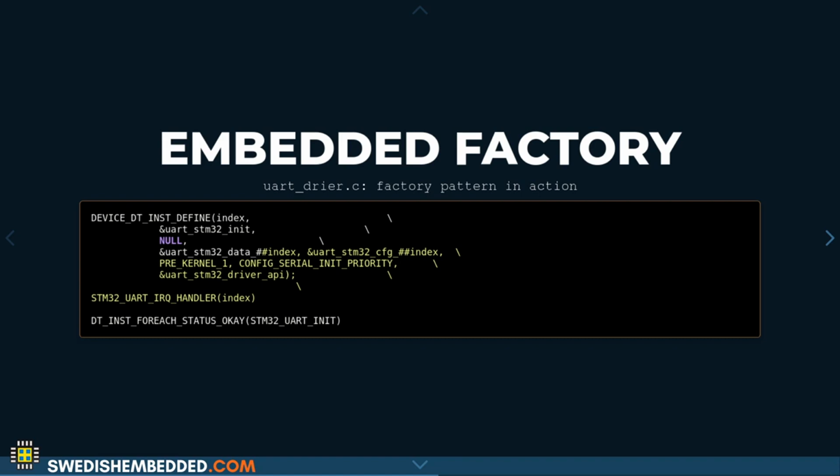This is a name that I've just created because I think this is a pattern that is very commonly used in embedded systems when you need to create objects before the main application runs, but it's not used as often in other places unless you use C++, in which case this is the pattern that is used automatically by the C++ compiler to call the constructors of your static and global variables. But that is a process that's completely transparent to you, so you're not actually thinking about it.